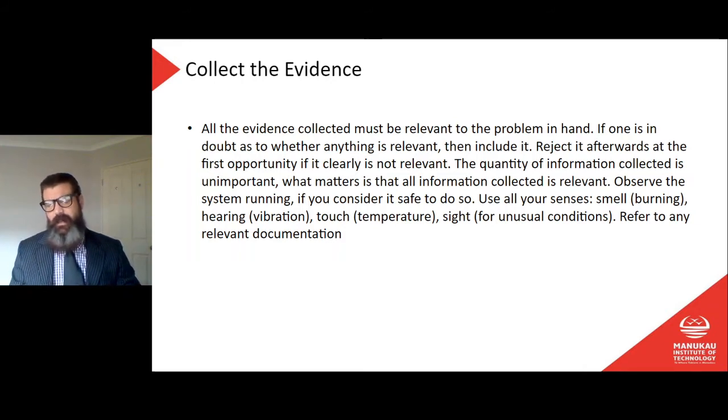It seems unlikely that it's 2 separate faults, one on the card reader and card reader screen and then one on the pump itself. What would be the common fault? So the first thing would be circuit breakers, and I look in the switchboard and I go, no, everything's fine. But then, okay, emergency stop switch.